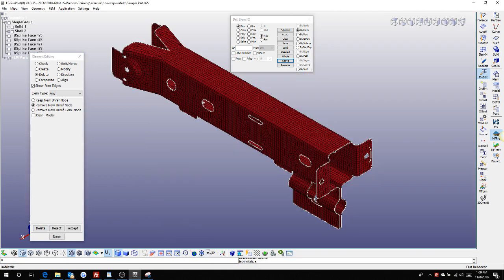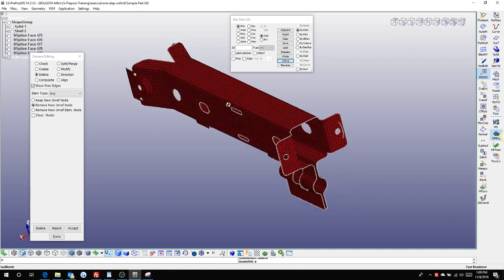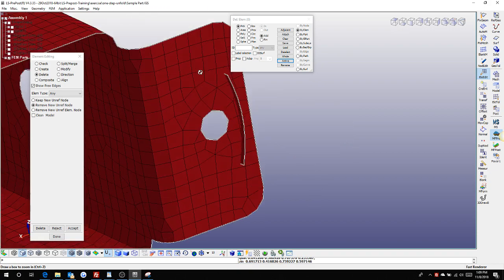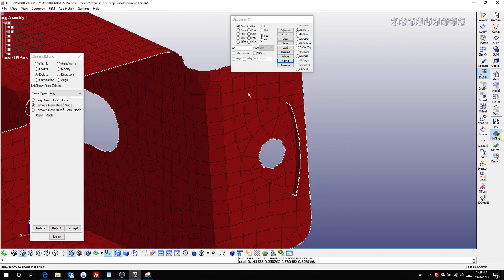And we can go out, take a look. We can see all these look good, and this doesn't look very normal. There must be some surface there that brought some mesh here. We're going to delete that by pick, and there are more than one, so I'm going to use propagate and then angle.